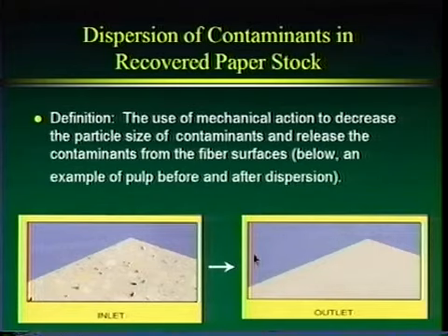And then after we apply mechanical action, we can get paper where those large specks that are offensive have been broken down into smaller pieces. Now, this came out of a magazine, a vendor for a disperser unit, and I believe it's an exaggeration. I also think there was probably some kind of bleaching process and perhaps even a washing, or more exactly a flotation process, to get rid of some of the ink and contaminants that have been broken down. But this is the idea. This would be the perfect case scenario.